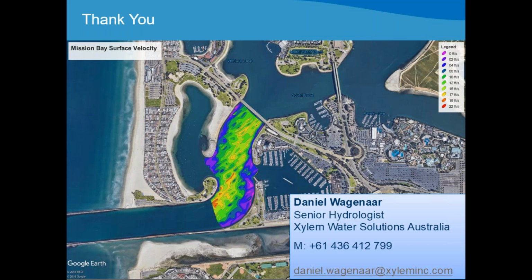You seldom get organizations that have that, and it's more used in rivers like the Amazon and deep channels. Mostly I use between 3 megahertz and 600 kilohertz, and those instruments' depth range is up to a maximum of around 100 meters, depending on the flow conditions and sediment, depending on the backscatter in the water and the sediment concentration. So no, these instruments are not able to have depth ranges of that kind.